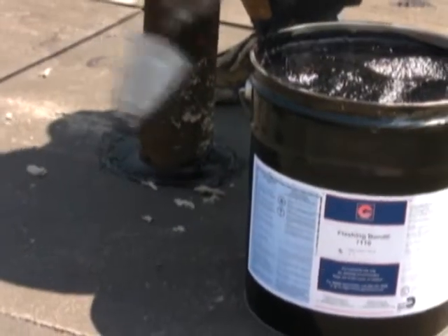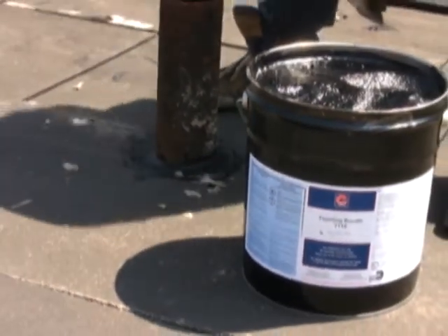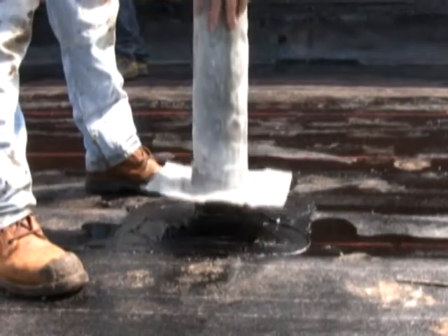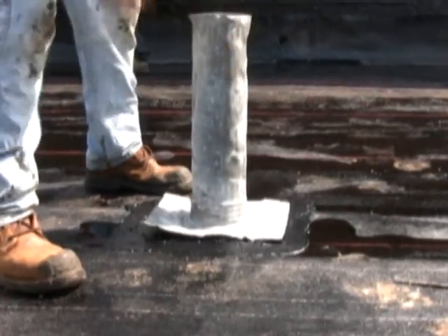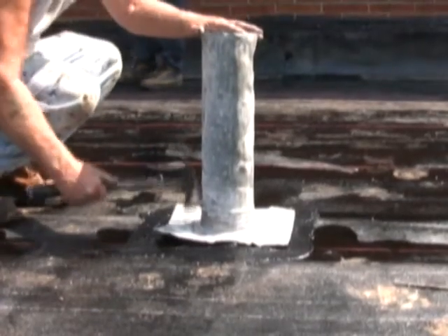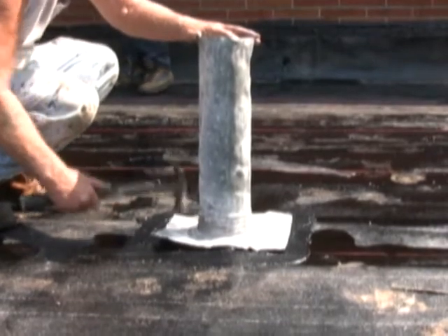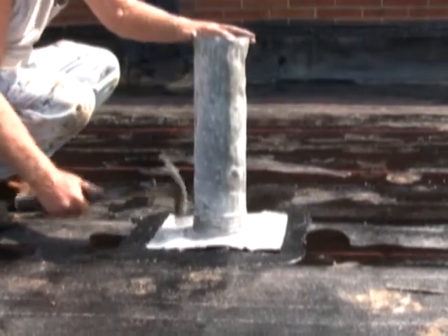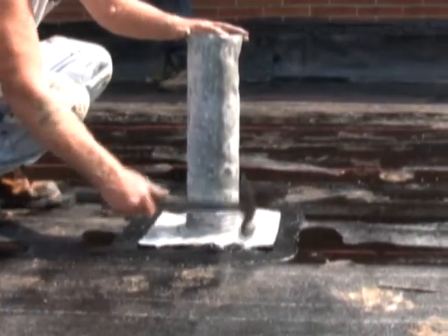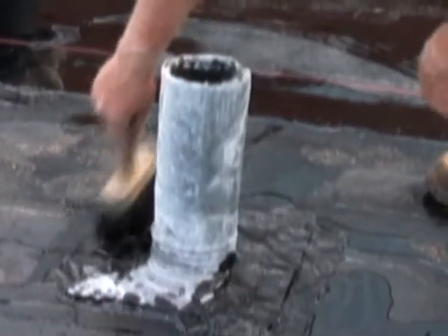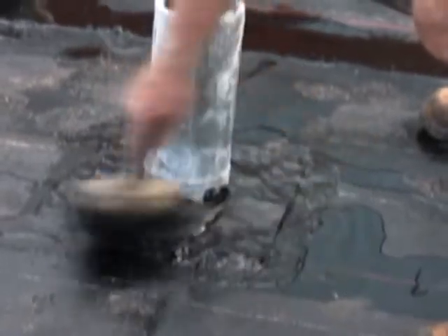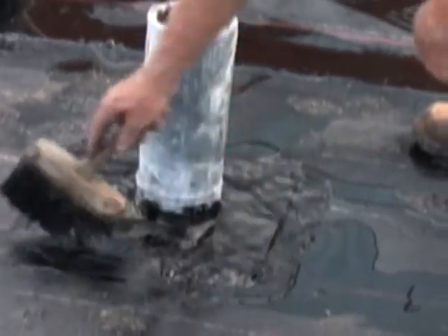Seal the base of the plumbing stack with elastomeric sealant. Install properly sized sleeves set in a 1/4 inch bed of roof cement. The flange should extend a minimum of 4 inches onto the field of the membrane in all directions. Next, prime the flange of the new lead sleeve with the appropriate primer based upon the bitumen utilized in the installation of the field plies.